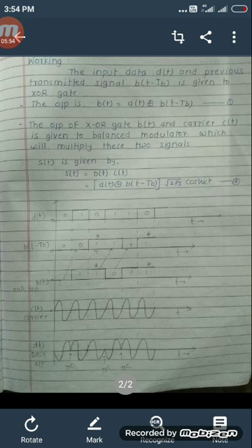And as we know, according to the truth table, the output of the XOR gate will be logic 0 for the same bits, and will be logic 1 for different bits. Meaning if the input is 0 0, then the output of the XOR gate will be 0. If the input is 1 1, then the output of the XOR gate will be 0. If the bits are different, meaning 1 0 or 0 1 is the input for the XOR gate, then the output of the XOR gate will be high, that is logic 1.